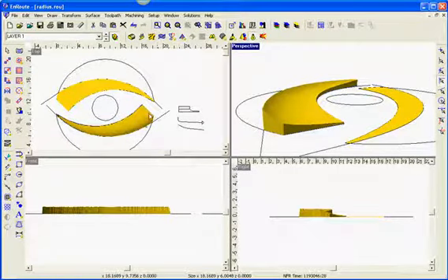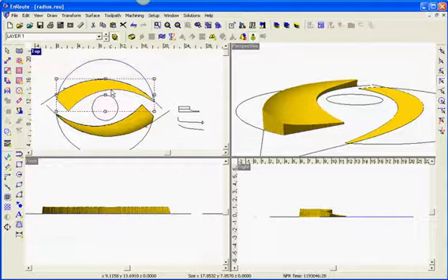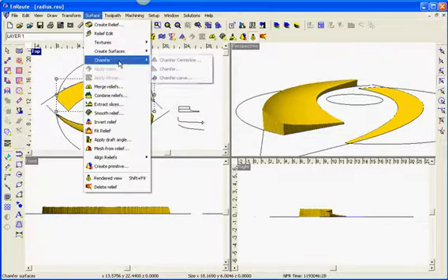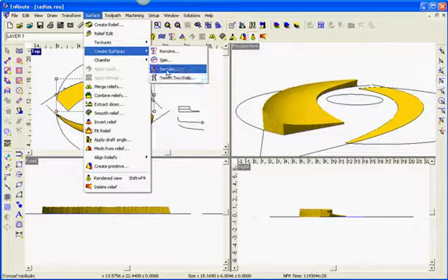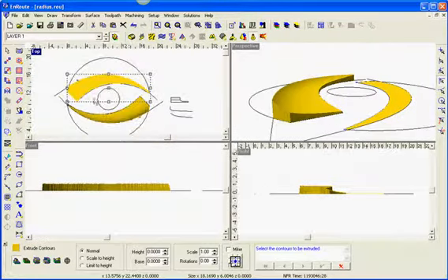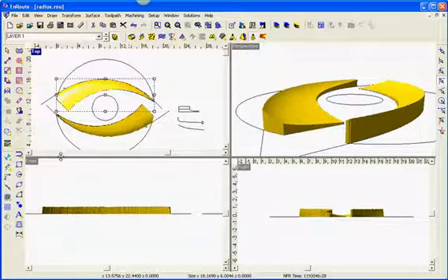All right, and now we can do the same thing with this one. We're going to come here to surface, extrude, and I have to have my relief selected first. Select the contour to extrude, which is right here. Select the path to follow, which is right there. And I already have add checked. So this creates my other sweeping part.